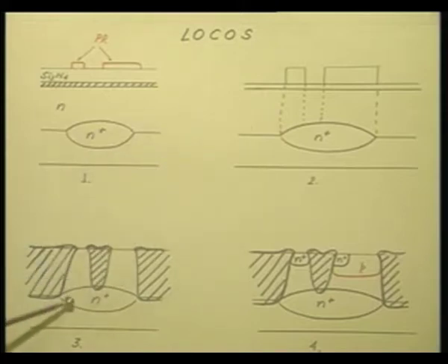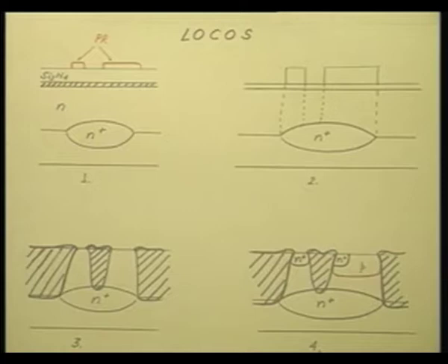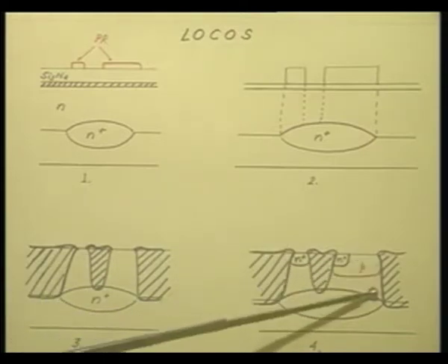So, after this, when you carry out the oxidation, this is how the surface looks. You carry out the oxidation and then you remove silicon nitride from these remaining portions also. Okay. So, you see this is your N plus buried layer, and on top of that you have realized these two regions. Now, in one of these, you carry out your base diffusion.